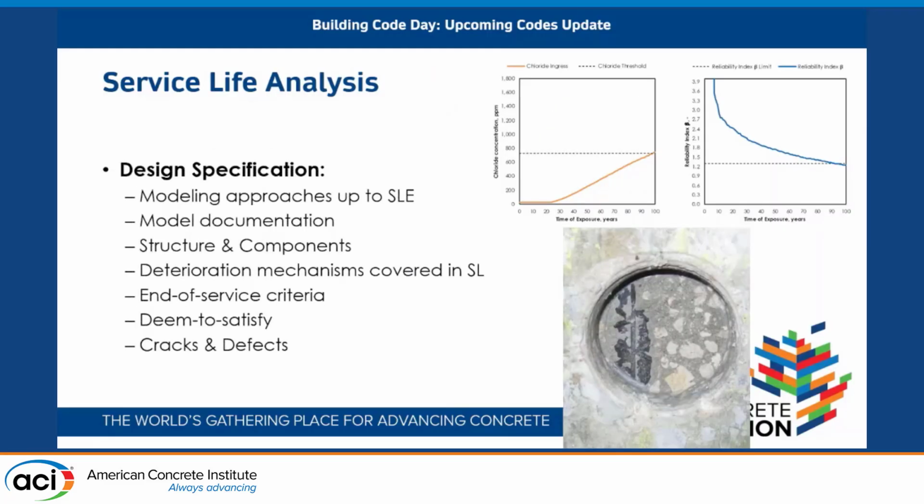Currently, we only have good tools to model corrosion, chloride ingress from de-icing salts or marine environment. Over the 25 years where service life prediction efforts have been made, probably 90% of the work has been done on corrosion. And it makes sense because it's the most common deterioration mechanism. But for other mechanisms, like I mentioned already, ASR and similar, we don't have good understanding.